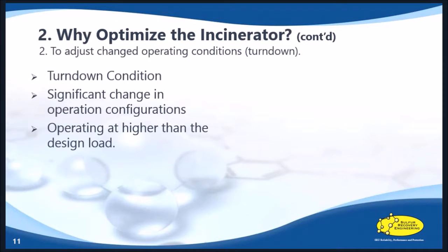In Alberta, many gas processing facilities are facing the problem of turndown, which comes with a reduction in the quality of acid gas. This not only affects the overall recovery efficiency of the SRU, but also warrants incinerator and stack performance evaluation. To meet the environmental constraint under turndown conditions, the facility may need to revisit the old set points, such as stack top temperature.